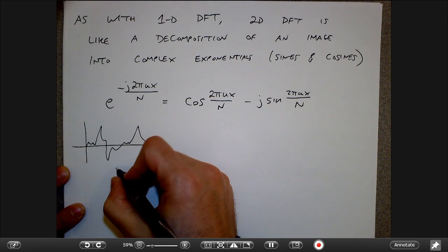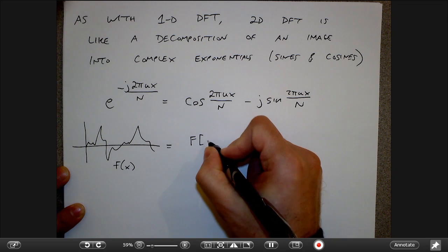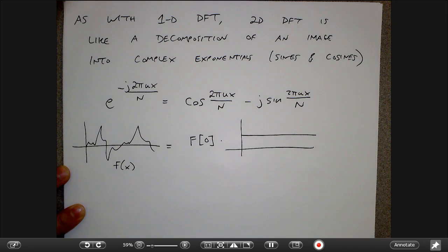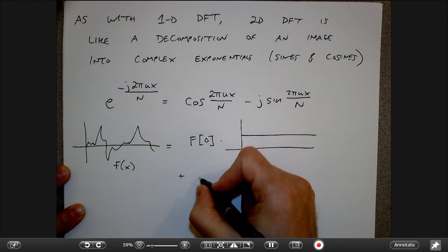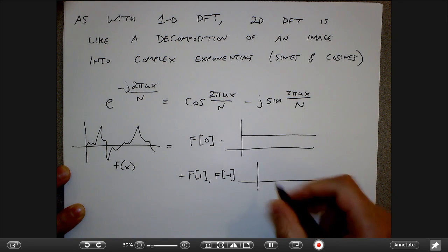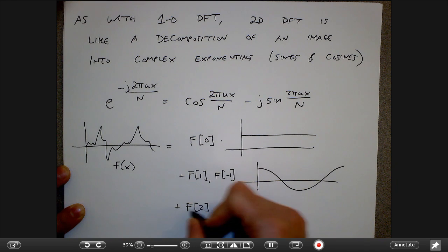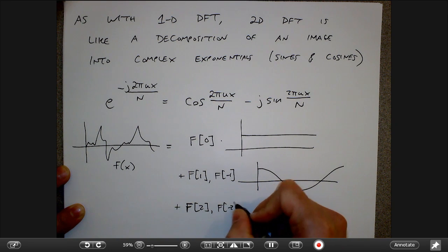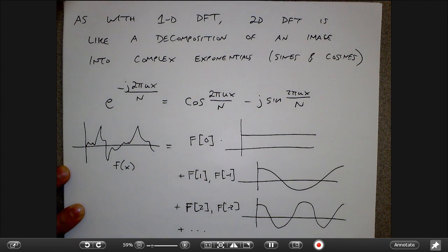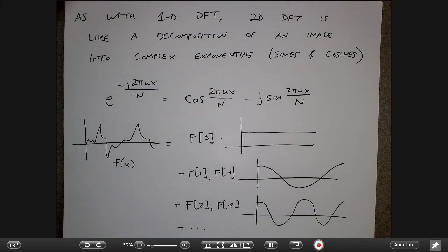I have some input signal, and here I'm drawing it like a continuous line because it's easier to draw that way. So if this is my input signal x, really what I'm saying is the first DFT coefficient corresponds to the weight on a constant term, DC. Then I have some coefficients that sit on sines and cosines that vary slowly, and then I have coefficients on sines and cosines that vary twice as fast, and so on. So that's the kind of Fourier intuition.